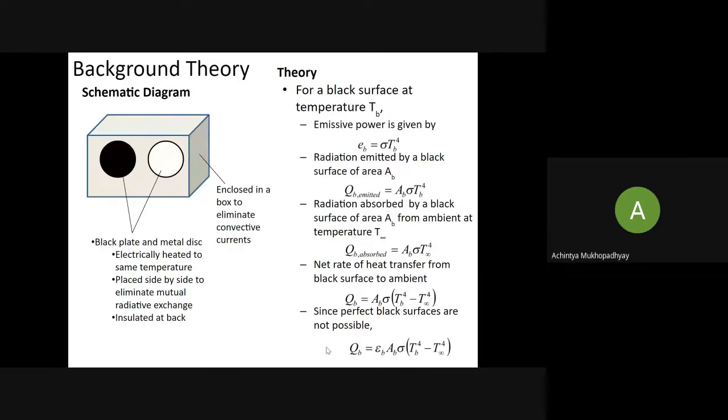The problem is that there would always be some convection. Once steady state is reached, the heat lost should be equal to the heat being supplied, so it is not a big problem to know how much heat is transferred from the plate under steady state condition. But the difficult part is to segregate how much of it is removed by convection and how much by radiation.